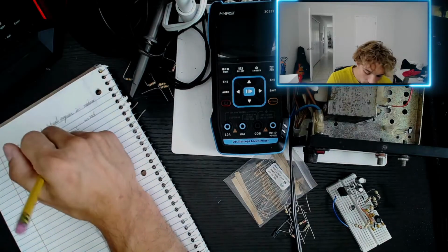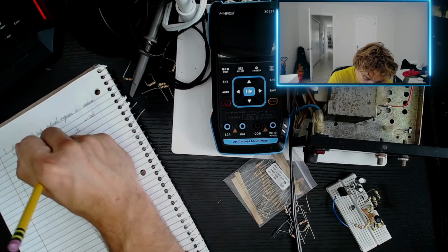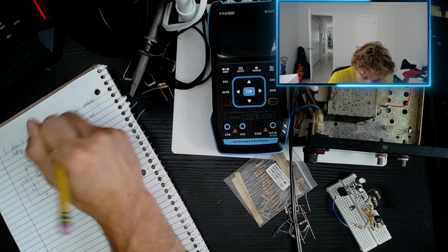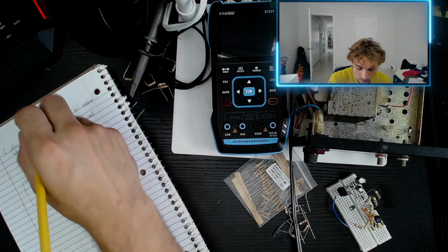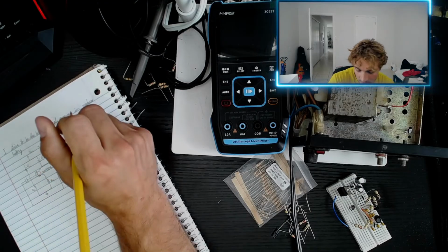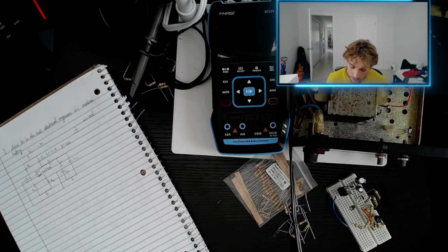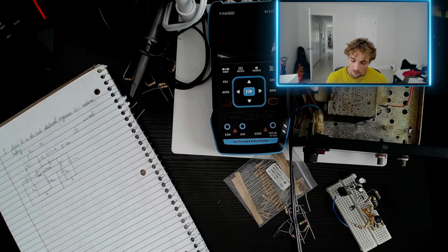So let's first set the desired collector current. We're going to say IC equals, let's go for 2 milliamps. This is what we desire. Okay, IC equals 2 milliamps. We're going to assume a value of 100 for our DC current gain, right? We're going to denote this with beta. So our beta equals 100.